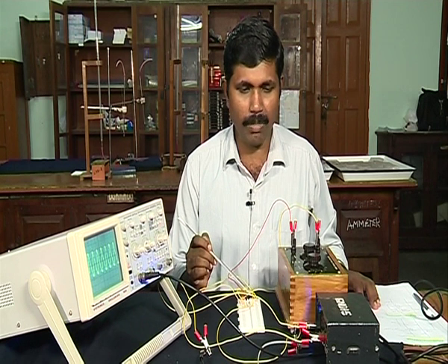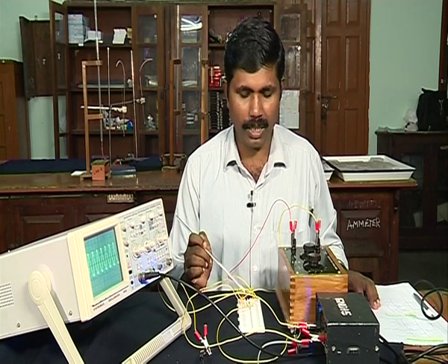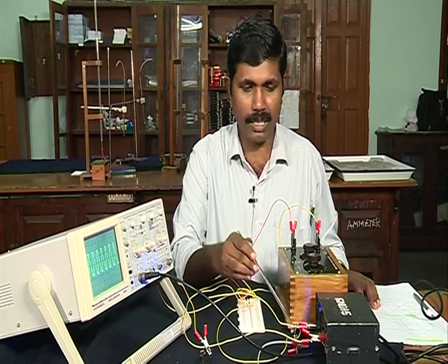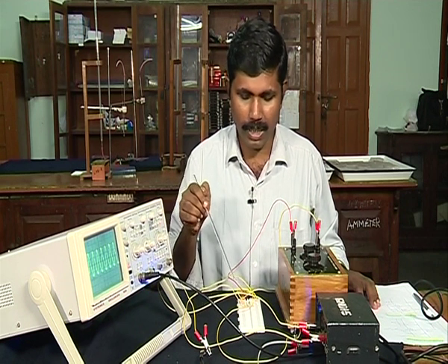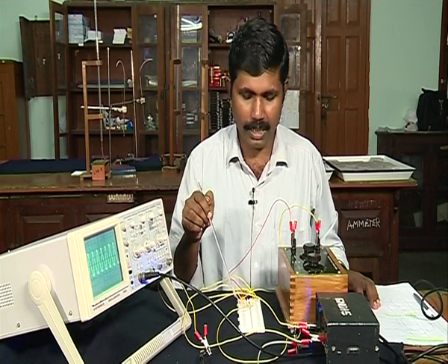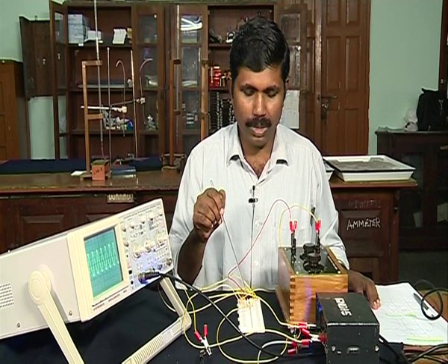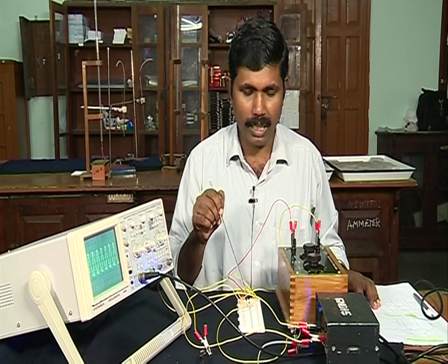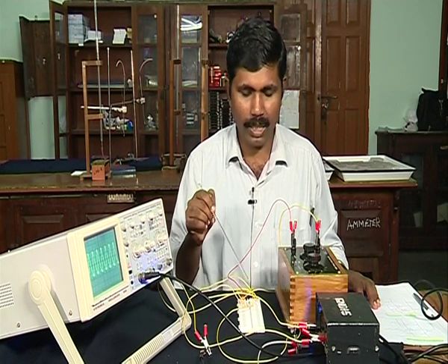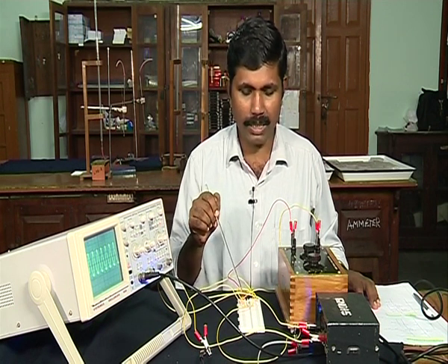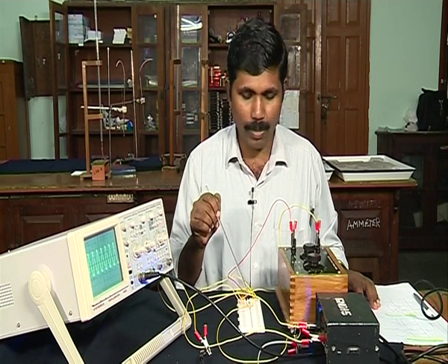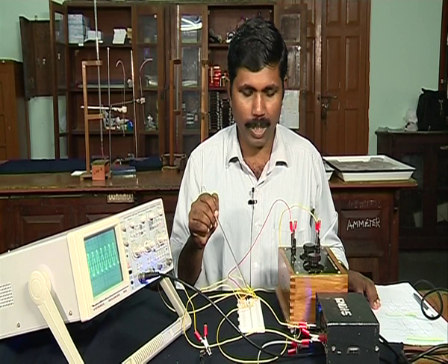First, the transistor should be biased. Biasing is done by a voltage divider biasing network. The positive supply of the power supply comes to the biasing resistor, which goes to the base of the transistor. Then to the power supply, the tank circuit is connected. That tank circuit consists of 2 capacitors and 1 inductance coil. Here we fixed the capacitance values as 0.1 microfarad and 0.01 microfarad.